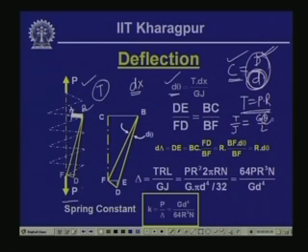So, theta for a smaller element, as we are looking into d theta, is equal to T L by GJ, and L here is the dx, the length dx for this particular element AB. Now, if we think that A is fixed and B is moving, then d theta will give the rotation of the segment AB.